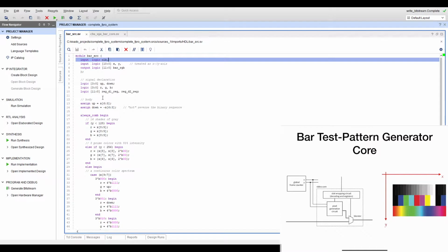However, for the whole video subsystem, for the sake of consistency, because one of the cores will need a couple of clock cycles to generate its output from receiving the X and Y, we will impose this particular restriction on all the cores. Whatever core you have, it will take the X and Y, and it will take a couple of clock cycles to completely output its result. This is the assumption we're going to make, just because one of the cores needs it.